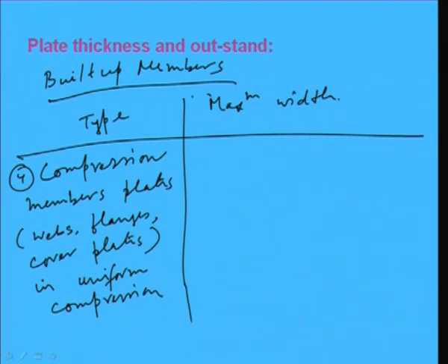For this, the maximum width will be 1440 T by root over Fy, subject to a maximum of 90 T.